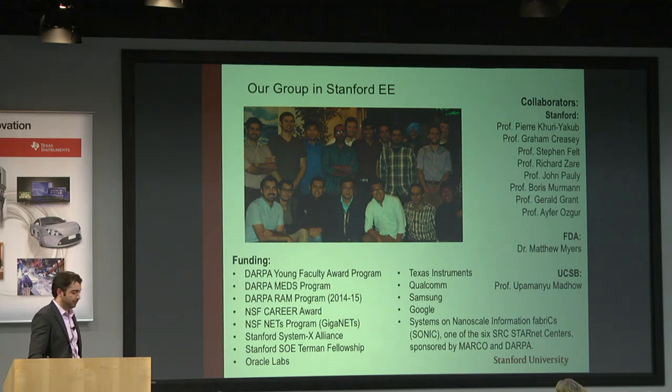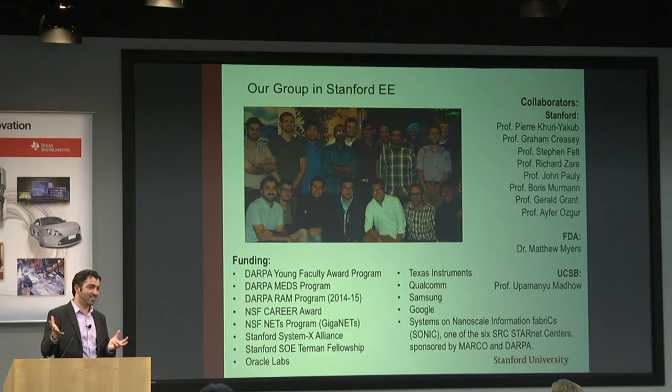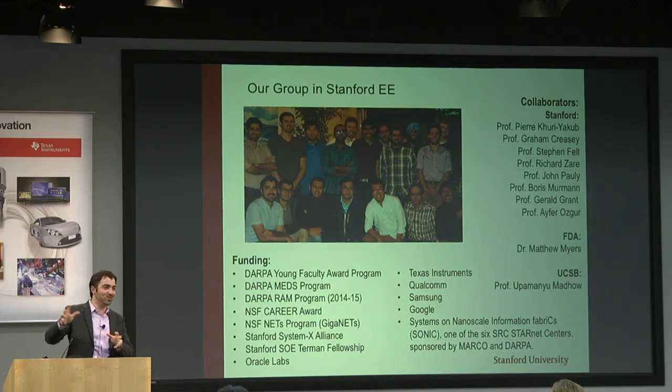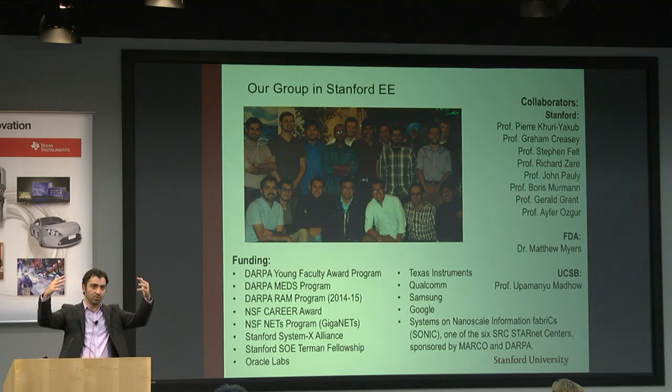Yeah. So our bread and butter is always a form of SAR. Here you get into trouble because you call it one thing and others call it different things, so I'm just going to call it frequency domain SAR. That's the one we predominantly use for most of our applications. We have also worked on time reversal techniques. What time reversal does is that you backpropagate the field to a given interface, and then you can run another algorithm. For example, we're looking at backpropagating to the surface and then doing a SAR going back. So those are the things we've looked at.